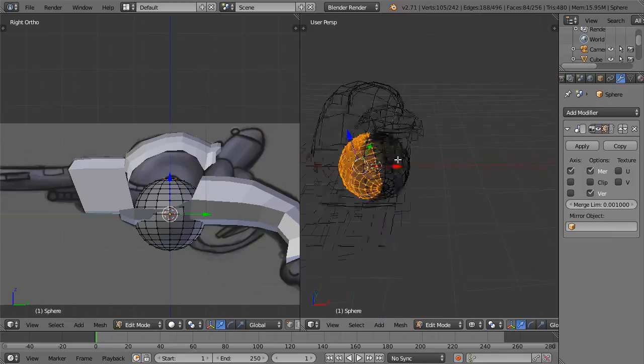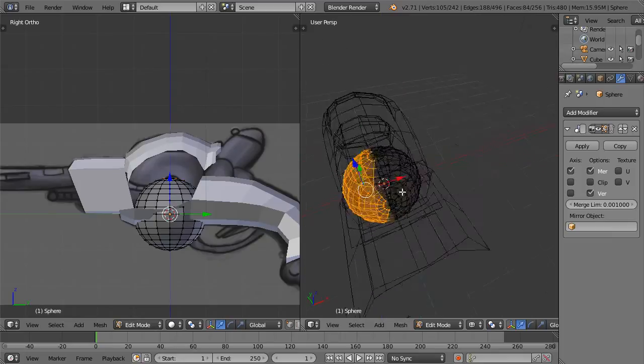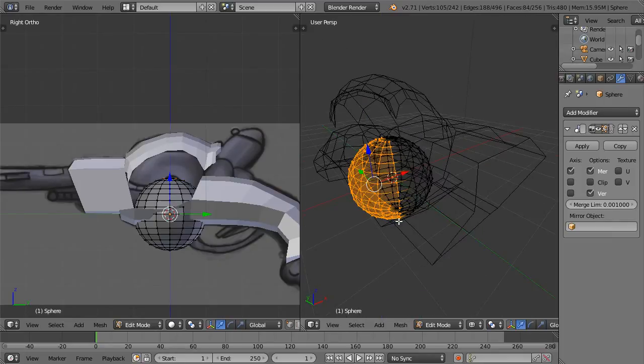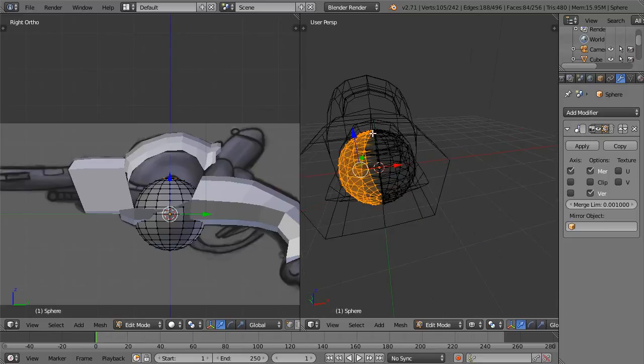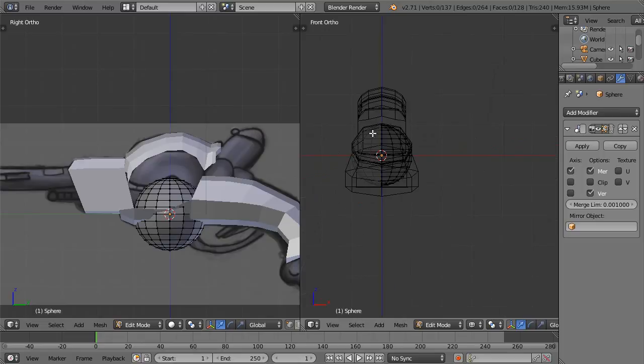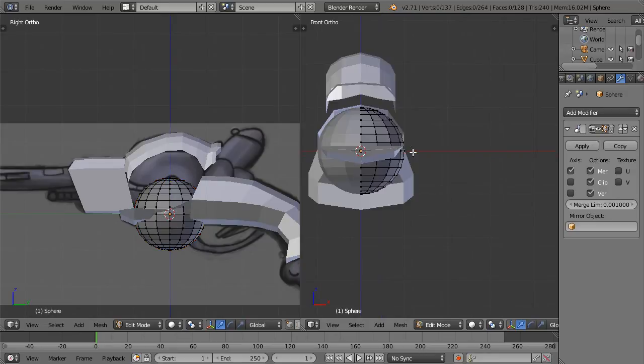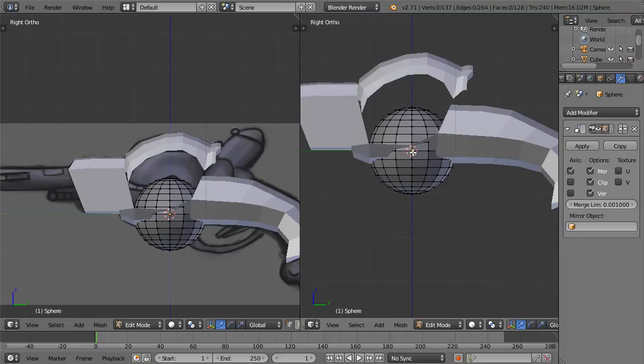And what that's going to do is basically take all the edges of the mesh and remove one selected area. So now I can delete my verts, and now I can hit clip, and I'm going to just be absolutely sure that everything here is centered. Okay, now I've got my fancy little golf ball.